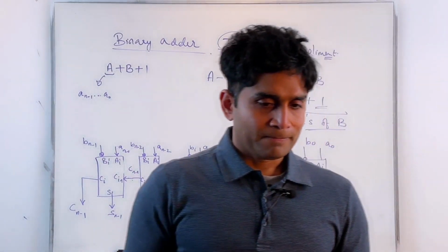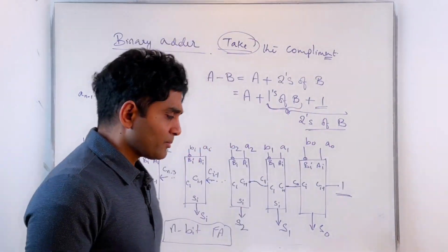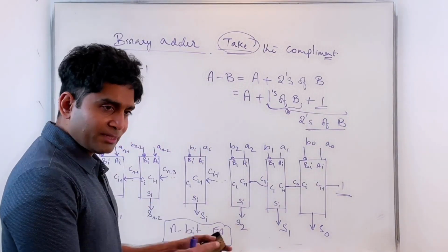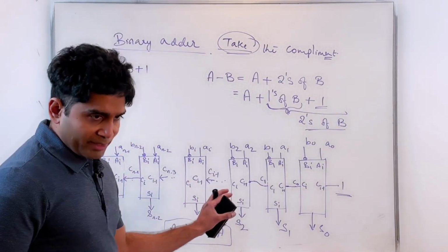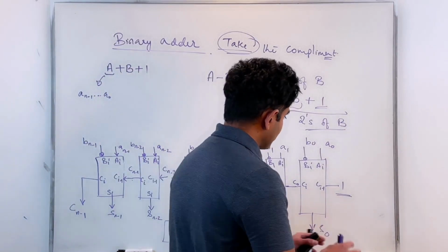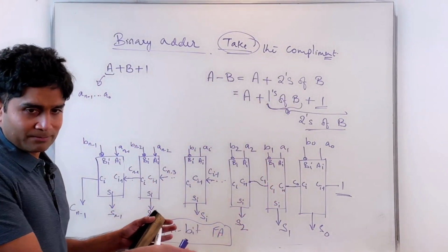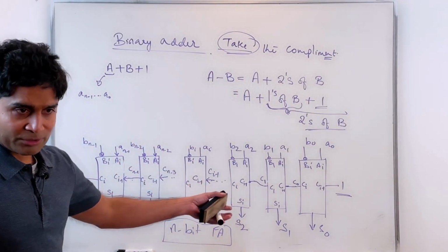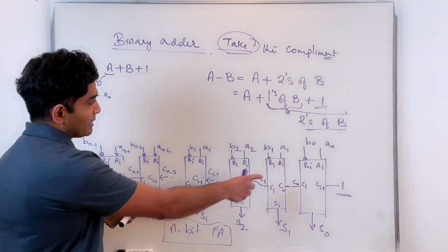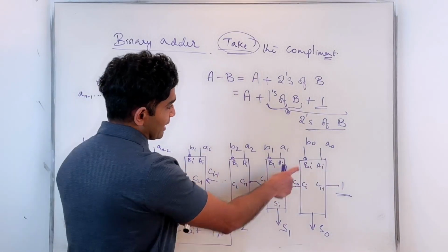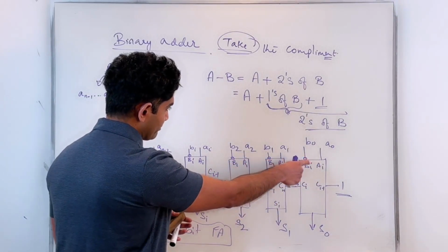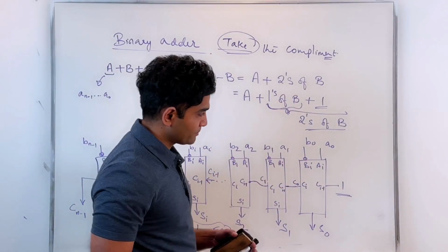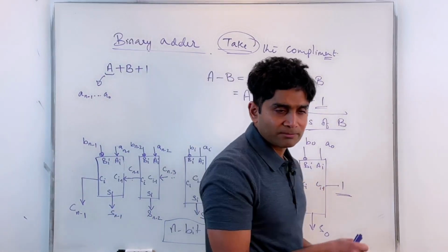All right. Now this is well and good, but as you can see here, when I do this modification, this particular circuit performs the subtraction operation. I cannot again reuse that as an addition operation, right? Because if I want to reuse that, I need to go back to my hardware and make sure that these inverters are not there, and I make sure that this is grounded.